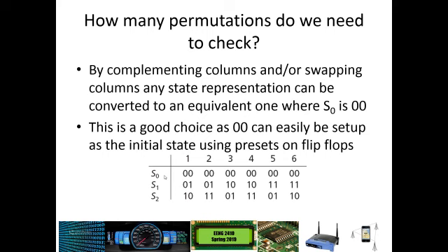And you also might take note that it's a good idea for our initial state to be 0, 0. And that can generally be set up pretty easily. That way we can just use a reset on our flip-flops and make sure that upon reset our state goes to all zeros. And so in this case we're only going to consider states where the default state, the initial state, is going to be 0, 0.